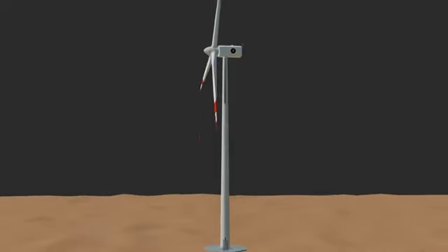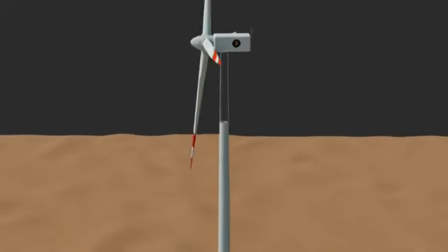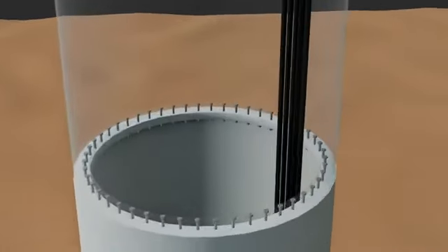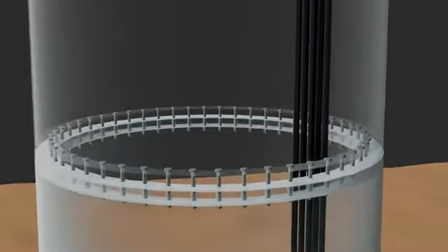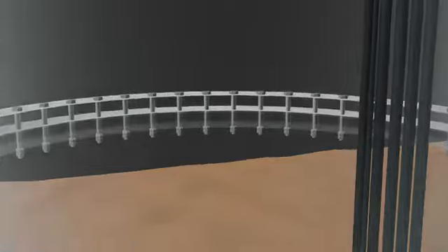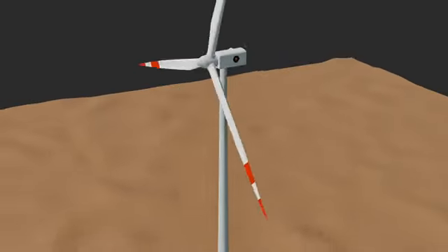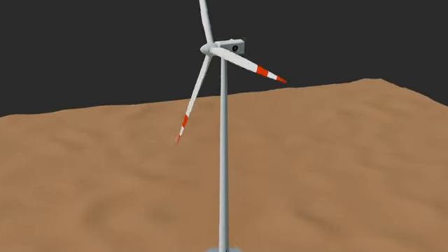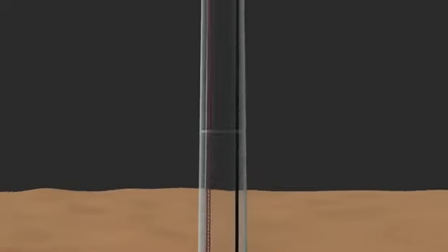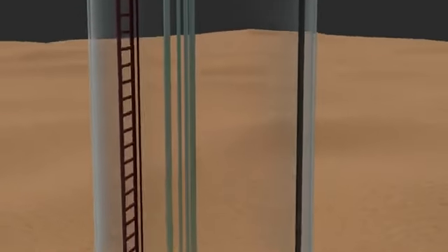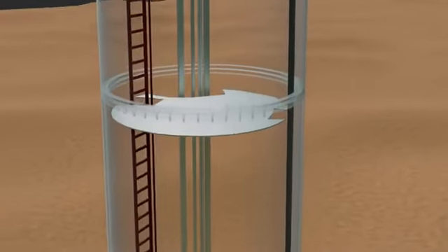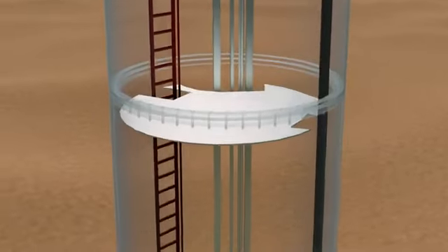top. The tower is a hollow tubular steel structure constructed from multiple segments, typically 3 or 4 sections for a 90-meter tower, bolted together with large flanged connections. Tower weight for a 2-megawatt turbine ranges from approximately 190 to 255 tons depending on height and design. The tower contains an internal ladder and a service lift for technician access to the nacelle. Platforms at segment connections allow safe climbing rest stops and facilitate inspection of flange bolts.